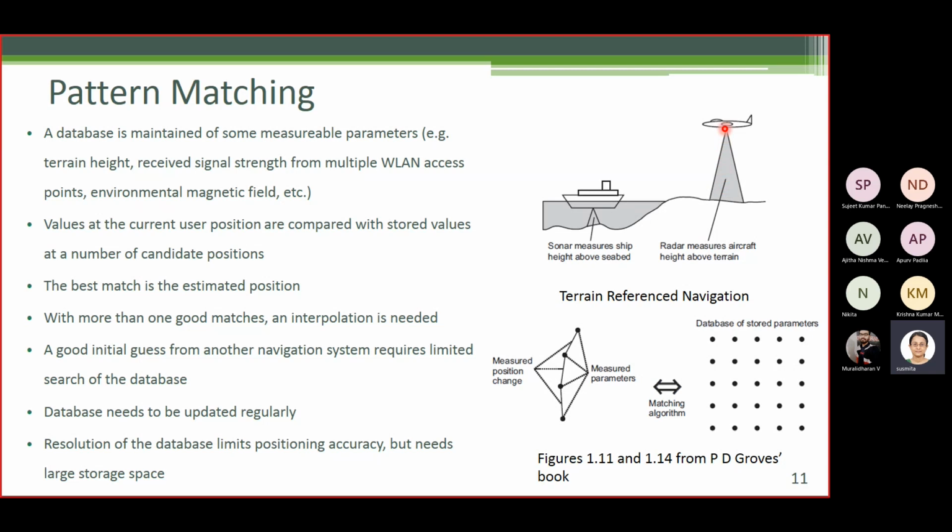By calculating the round trip time of the signal, we can find the altitude of the aircraft above the local terrain. Then, using some other navigation method, for example GNSS, the aircraft can determine its altitude above some other reference, for example Earth's surface. Later we'll see that the Earth is modeled as an ellipsoid. GNSS gives altitude above a reference ellipsoid.